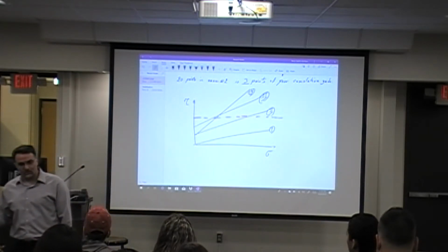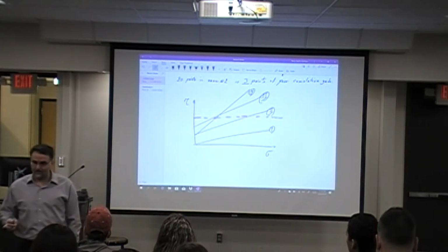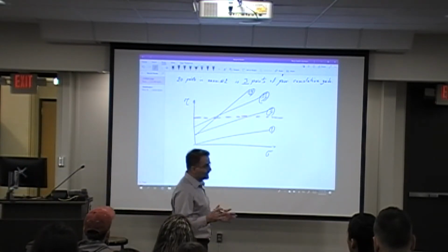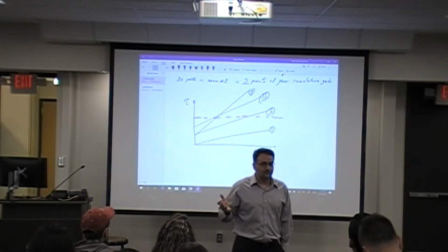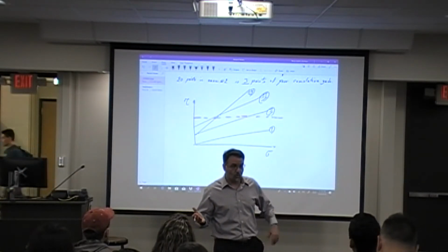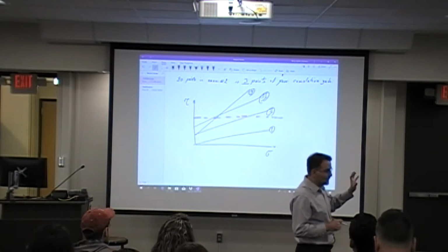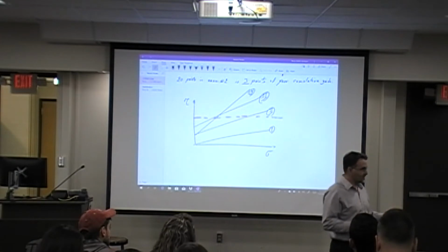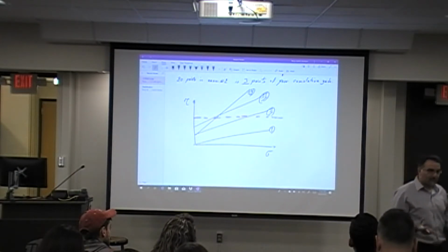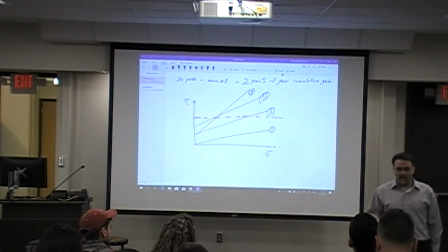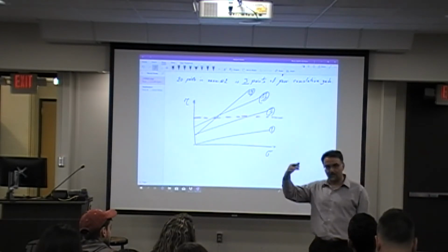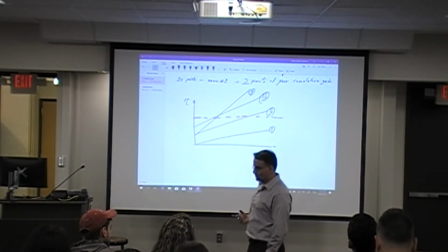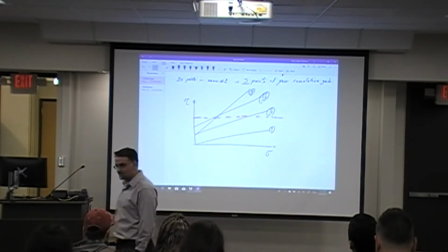Now the point there was to use the proper unit weights, right? In one case you had moist unit weight, the other case you had saturated unit weight. Moist unit weight means that it already embeds the component of moisture in it. It's not saturated, because we know that in natural state your soil has some moisture in it. That's why we call it moist unit weight. And then the saturated state would be when it is fully saturated, right? And you needed to make sure that your saturated unit weight shows in the total stress calculations.